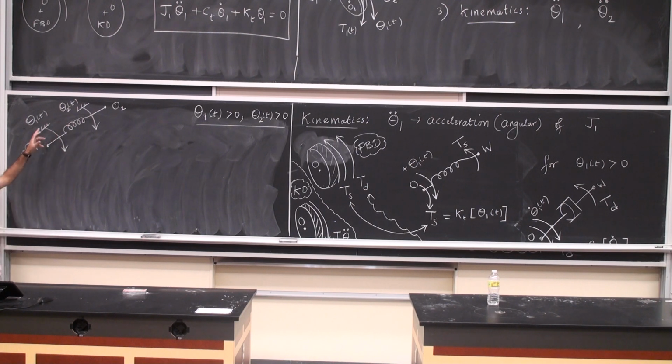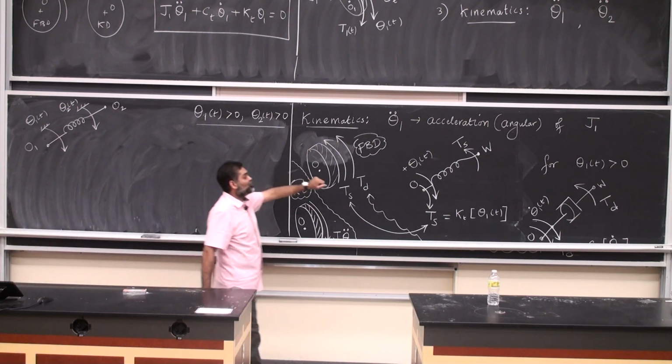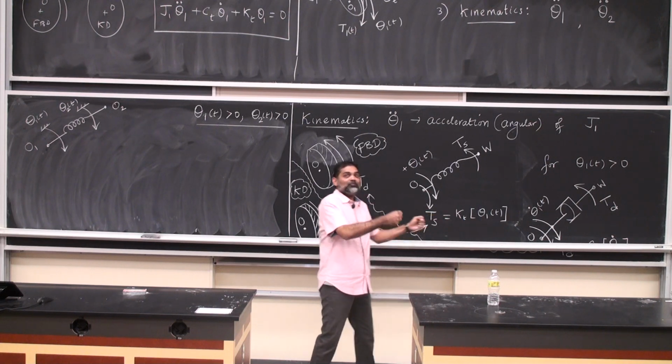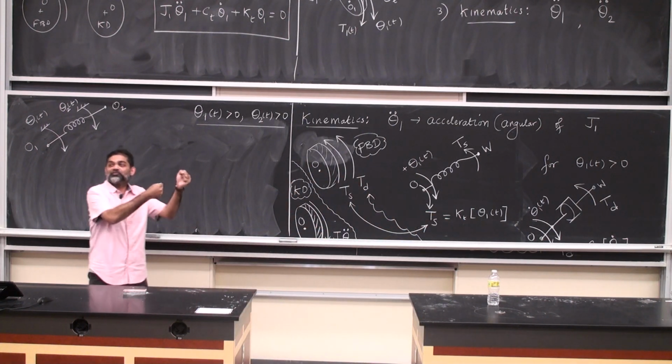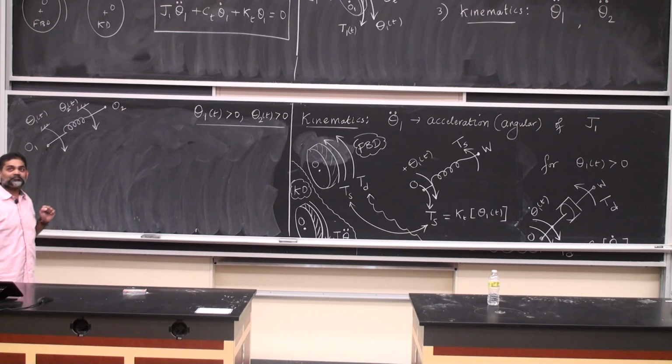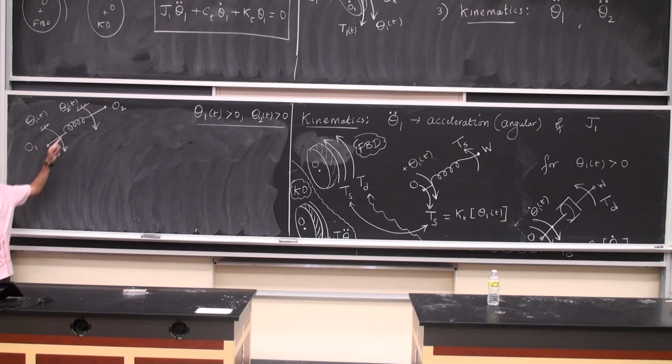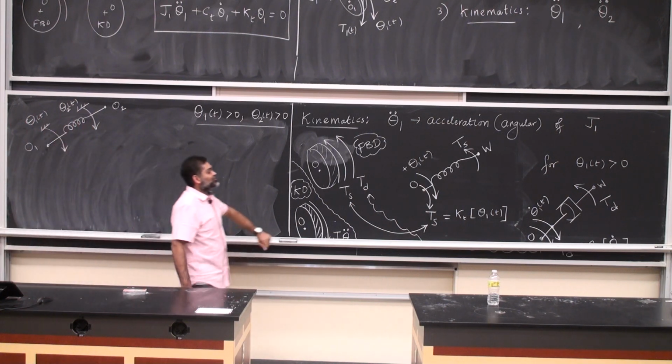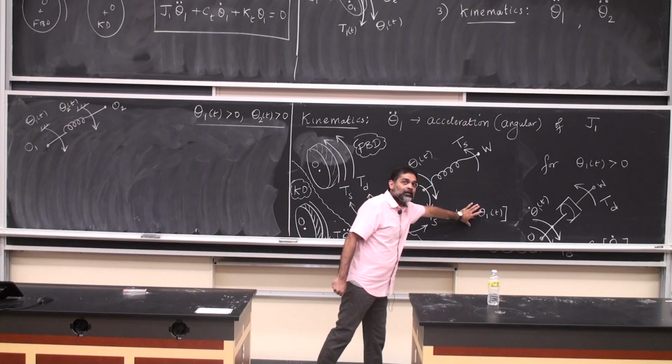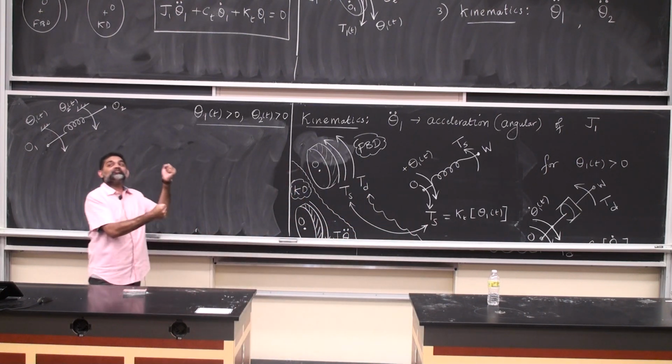And I'm going to repeat what he said. Because you're rotating θ2 and θ1 by the same amount, obviously the amount of torque to rotate this end by an amount of θ1 is going to be lesser than the amount applied here, because the system is anyway rotating in the same direction as θ1 due to θ2. Once again, because I'm rotating them by the same sense, that's important, right? The torque I need to apply here to twist this end of the spring by θ1 is going to be lesser than what I have here, because θ2 is anyway rotating the spring in the same sense as θ1.